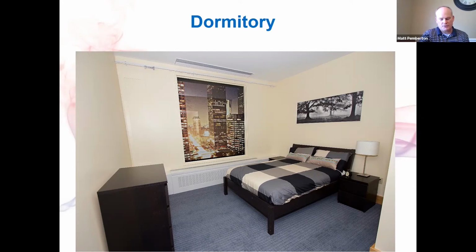When I say laboratories, it's too broad of a term, right? It depends on the type of laboratory you're doing and the filtration rate requirements. Some just have air change rates and some have air change rates required with filtration. So to say laboratory is very broad, and I agree with that. It wouldn't be used in a pharmaceutical laboratory, right? But a college bio lab is not that big of a deal as far as the filtration rate requirements. So when I say a lot of our labs, there are a lot of university laboratories, not sophisticated pharmaceutical type stuff. So I completely agree with you there. It all depends on the filtration rate requirements for laboratories.